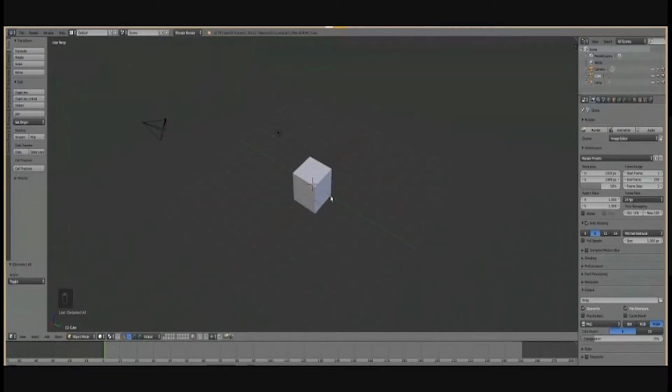If you want to basically pan this entire thing around, you hold Shift and the middle mouse button, and you basically can move it around. Okay, so there's a difference between moving it around like this versus moving it around like this. For moving it around like this, I'm holding the middle mouse button. For moving it around like this, I hold Shift and then I move it.